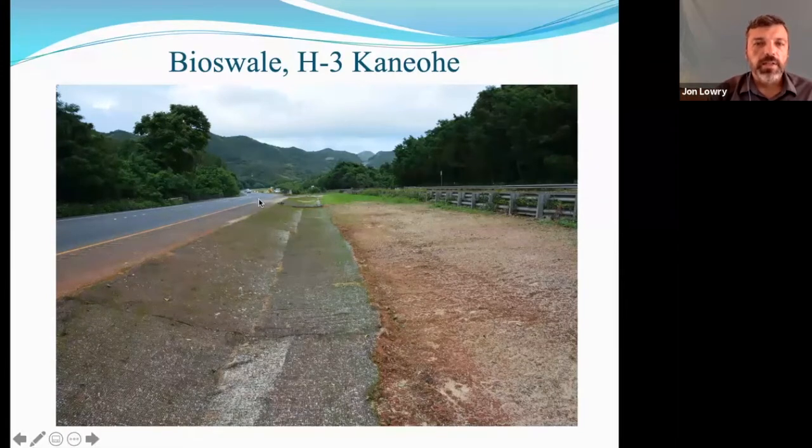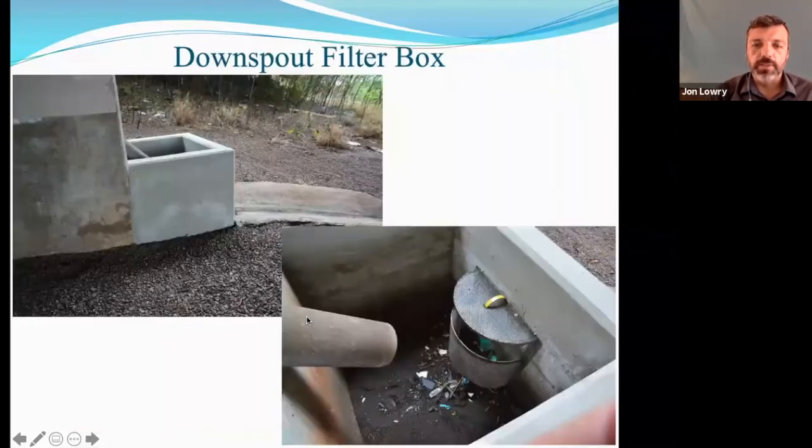And as you can see here, this is after the engineered soils have been installed, and then this is a biodegradable matting with the hydromulch on the surface. So now, instead of the water going directly off the paved surface into a paved concrete channel, it flows into this swale and is slowed by the surface grasses. Hopefully we get a good amount of infiltration into the aggregate layer and ultimately into the soil. And then whatever does make it into the storm drain has at least been filtered by the surface swale or the underdrain system.